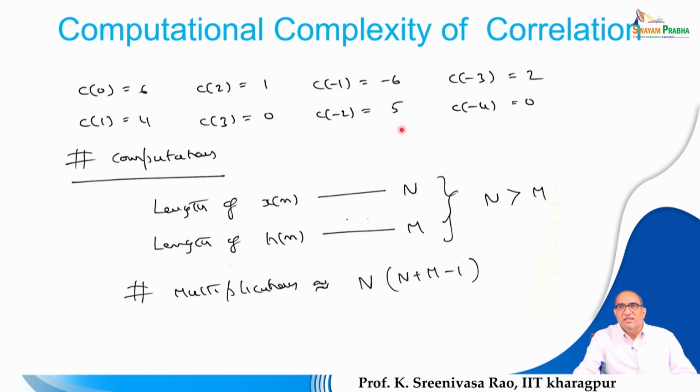Now we have seen that convolution and correlation concepts are very similar. In case of convolution, to visualize it graphically, out of two sequences one sequence has to be fixed, any sequence out of these two can be fixed, and you rotate the other sequence by 180 degrees, then you get the negative of that sequence, and that negative sequence has to be shifted or slid towards the positive or negative direction. For different shifts, you will get different convolution values.